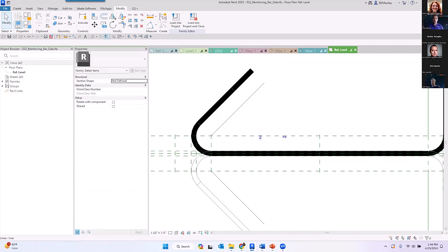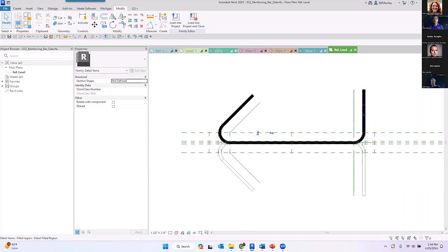If you have a trapezoid window family and wanted to lock the angle side of a specific angle when someone changes the width of it, yes. So you can start saying, hey, I'm going to change the angle if you change the width. Absolutely, I'd be locking those things to a reference line. So kind of like here, if the length changes here, I need this. This is still associated to that reference line. If the length changes, this is constrained to that. So yes, it can do that. Now, if you're in a 3D world and it's all one extrusion, you obviously can't make the whole extrusion associated to that reference line or make that your work plane. So yes, you're just going to be doing aligning and locking on those constraints.